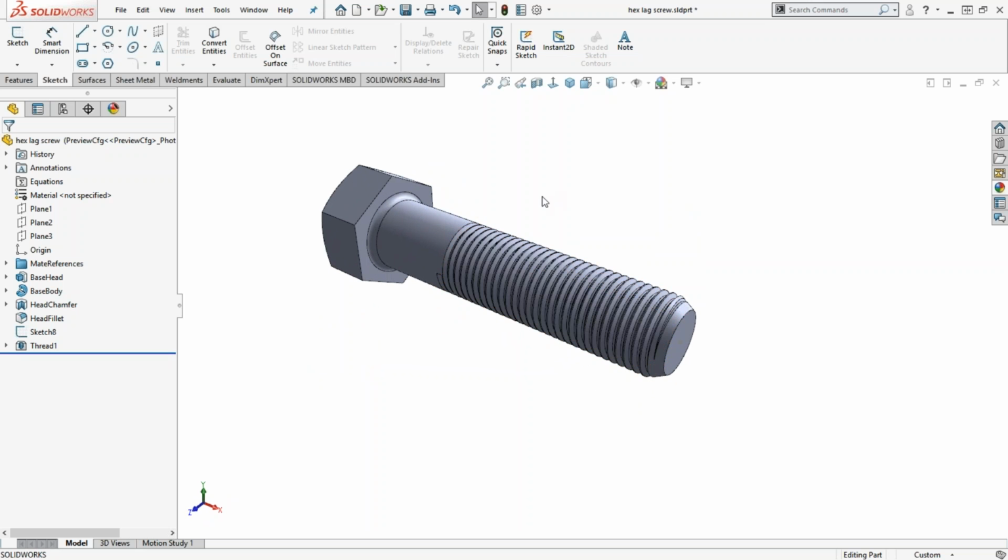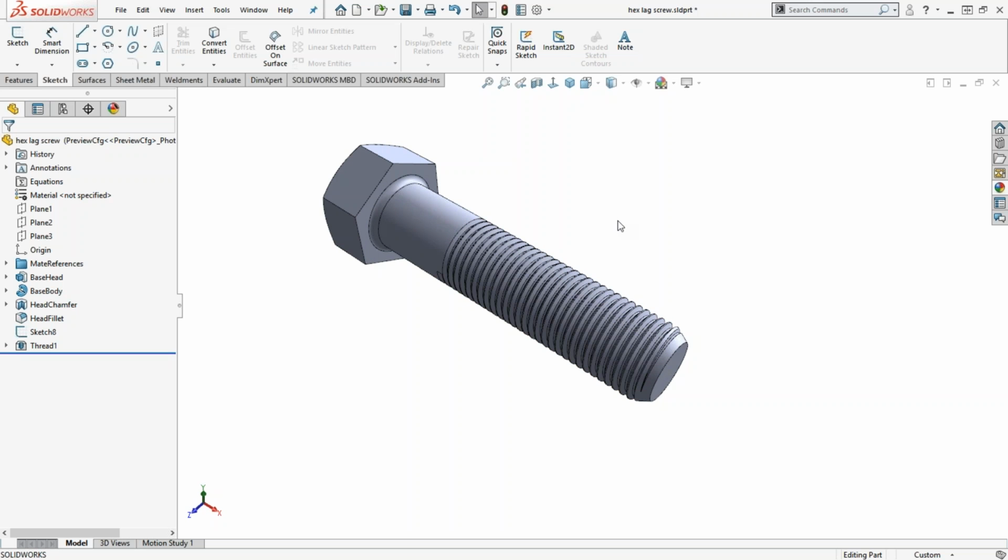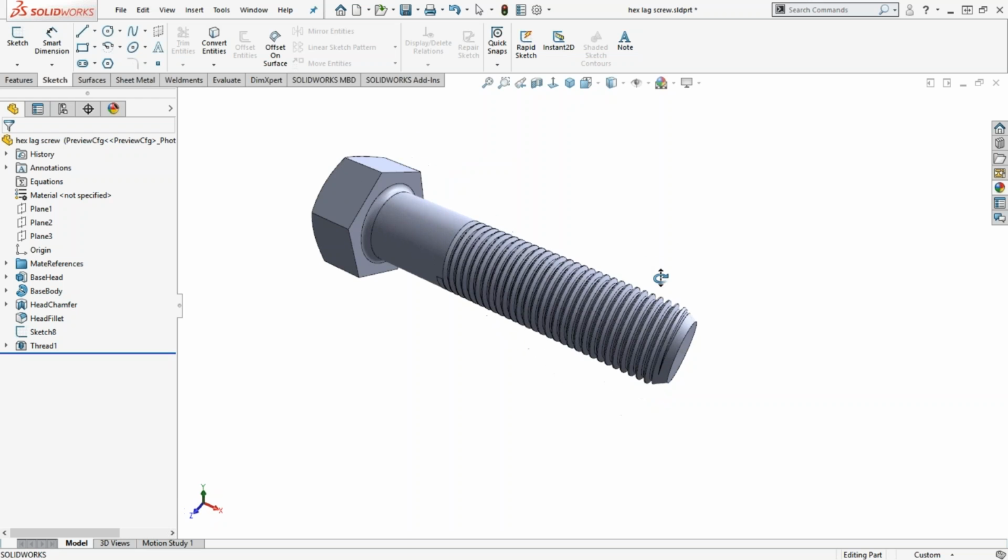So it's a lot nicer than if you're used to working with pre-2016 versions. You would have to create a helix spiral and 3D sketch, and then use a swept profile cut feature to create these threads in the past. And they were also pretty memory intensive, so they would take a while to rebuild, and it was just not that practical to actually model threads before this feature became available. And then still in large assemblies, it's much more practical to just use a graphical display of thread rather than actually modeling it. But if you want to get there, this is how it's done.